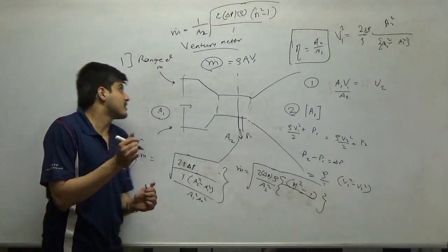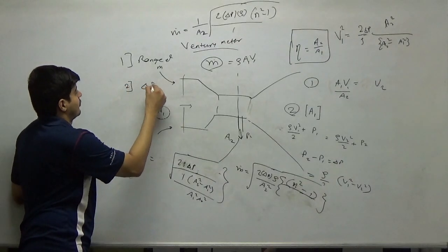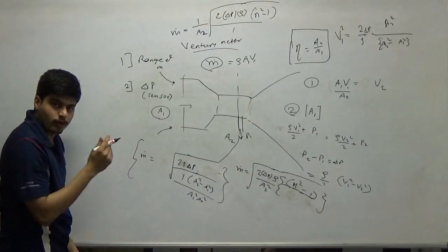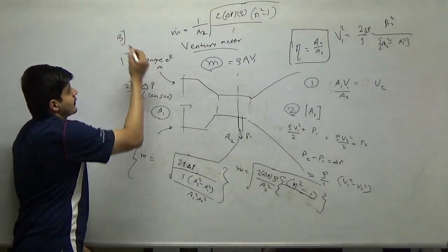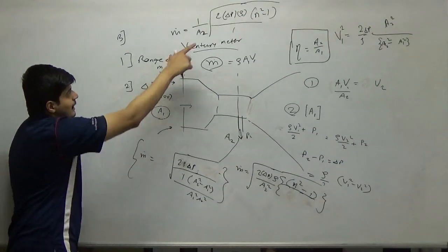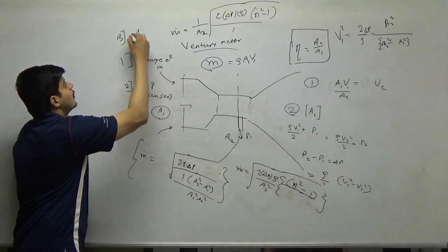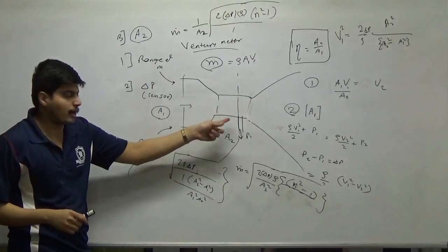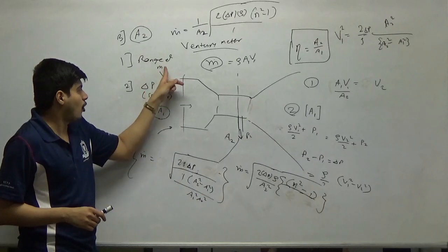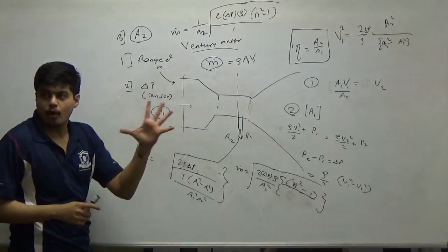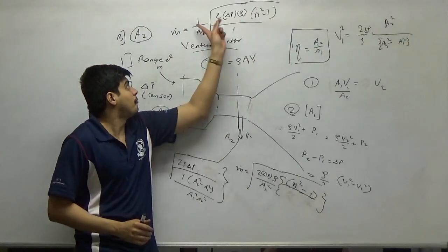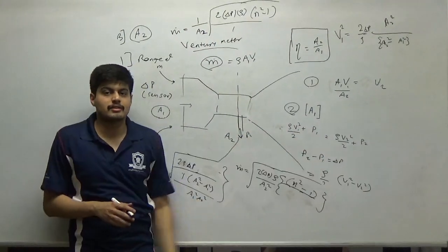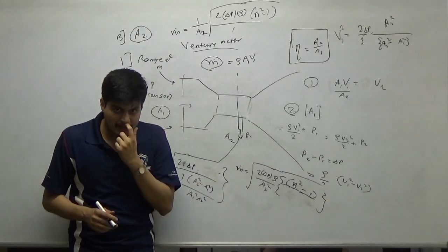So the three factors that govern your accuracy are the range of mass flow, lower or larger, which you are determining it for, the sensor accuracy with which the delta P is being measured, and A2, the least area itself in the venturimeter. Better the handle you have to eliminate these capillary effects, or the ranges of lower constrictions, or the pressure errors, better accuracy you will get in drawing. That's all about a venturimeter, which is a very important tool in aerodynamic experimentation measurement.